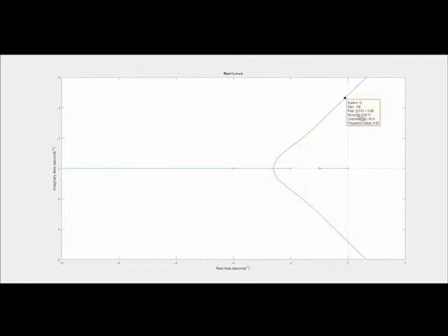This is down to the resolution of this plot. To the left, a gain of 182 is at this location, and to the right is 216. And we calculated by hand 216 exactly, actually. So we were pretty close. This tells you at what gain your system will go unstable.